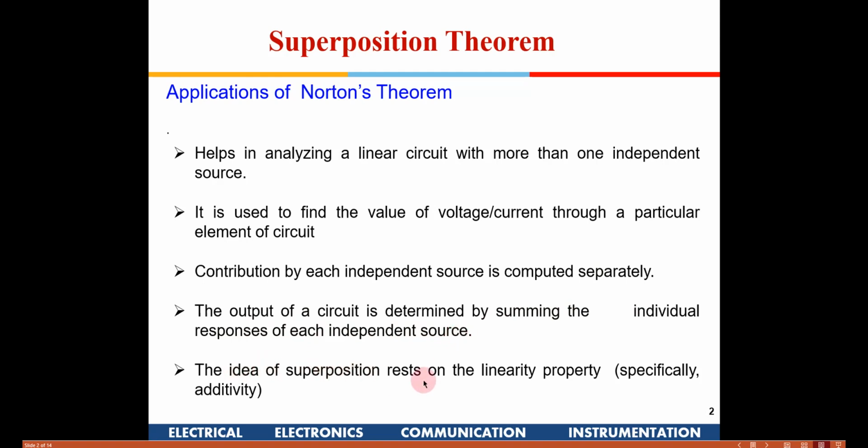The idea of superposition rests on the linearity property. That means the circuit has to be linear, like that was the case for the other theorems we did till now. Here also linearity is an essential property. Only then can we apply superposition.